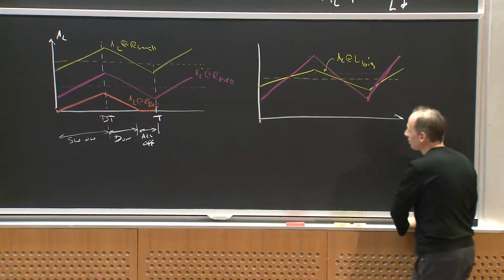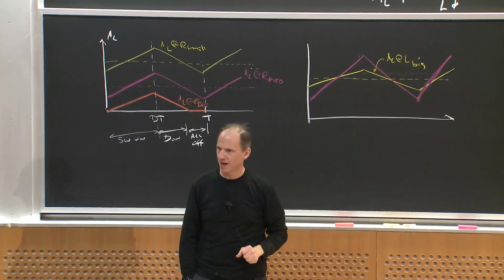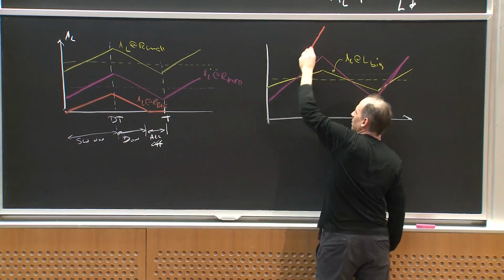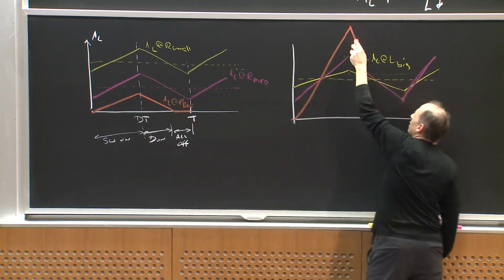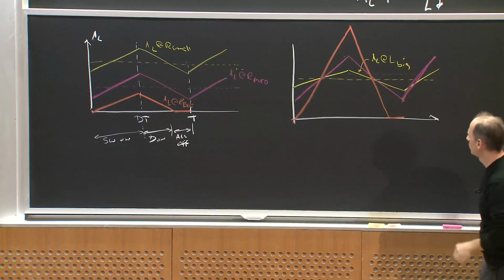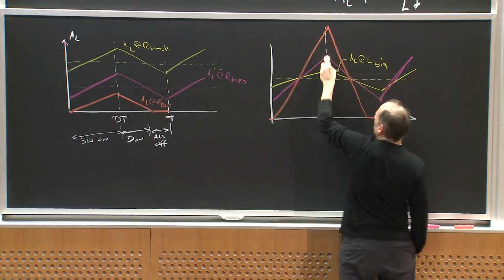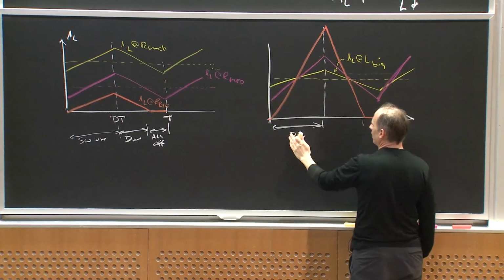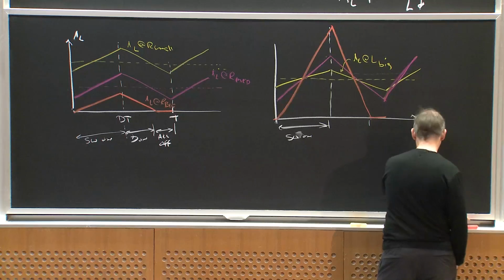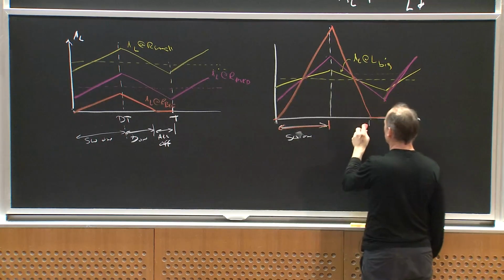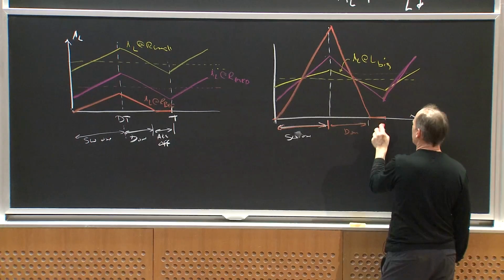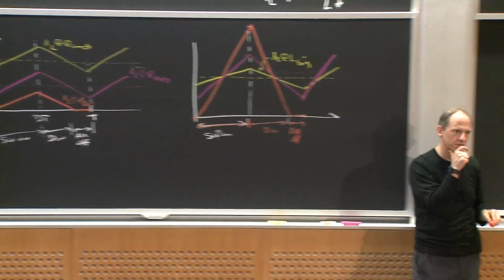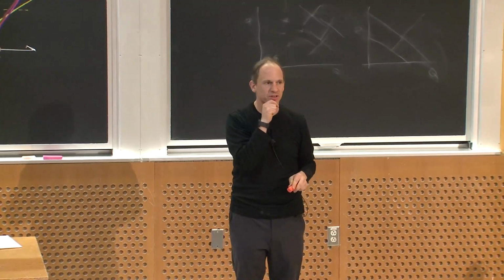Okay. If I turn the converter off and then I put in an even smaller inductor, what would happen? If I get a really small inductor, the smallest inductor I can find in my kit, maybe I get a waveform that does this. Starts at 0, comes down, hits 0, and then stays at 0. So I'm going to get, again, a case where I have the diode on, and then I have the switch on. In this case, and this is only pertaining to this bottom picture, the diode's on, and then I get a time period where both are off. And this is a different mode of operation. Any questions about that?